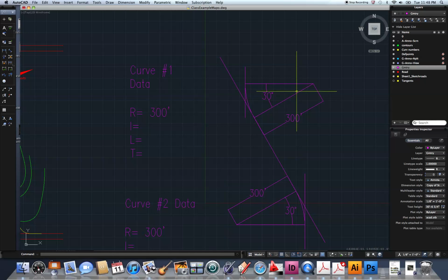Now, these dimensions I've been doing are annotation dimensions. I'm actually in the annotation view. Normally on the Mac version, when you first start, you will be in the drafting view. Sorry, my computer's giving me the rainbow of death right now. So here in the drafting view is where we normally have our tools. To switch to that annotation panel up here, you can go to annotation right there. In the Windows version, it will either be a pull-down menu up here or another option in all of your toolbars up at the top of your screen.